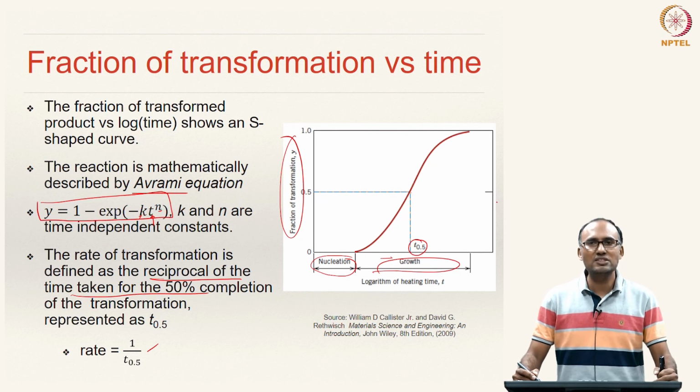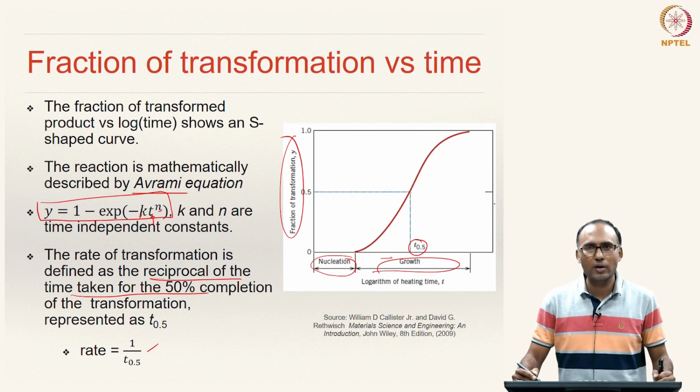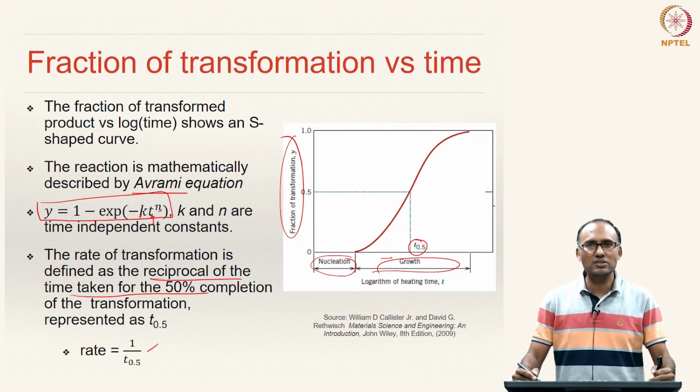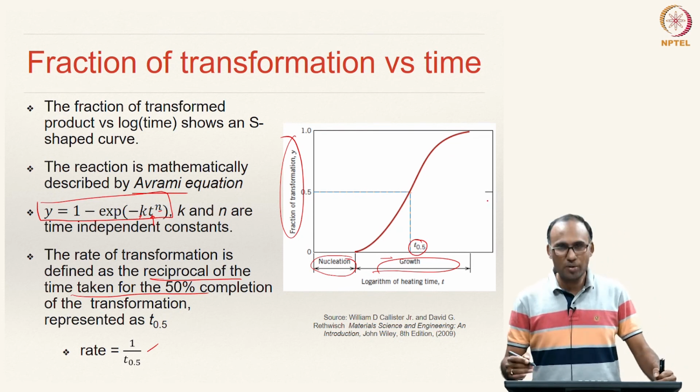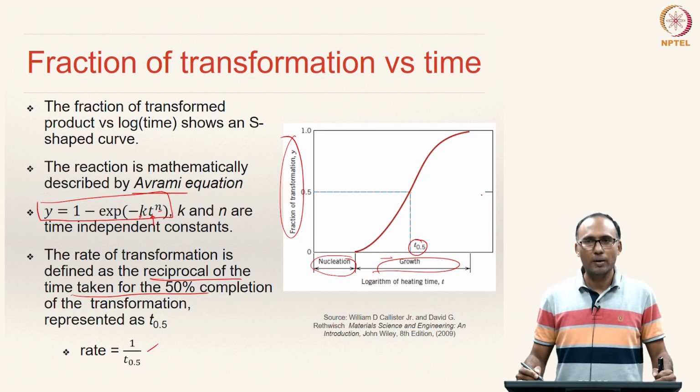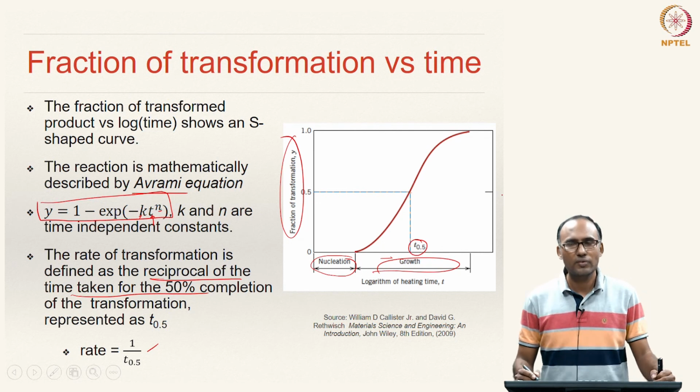And then we have discussed the growth process and how it is described by a diffusion-like phenomenon, and we have shown that the growth is higher at high temperatures and reduces at low temperatures, because at low temperatures the diffusion is low, and the overall transformation rate also is shown to have a maximum at a certain temperature below the Tm.